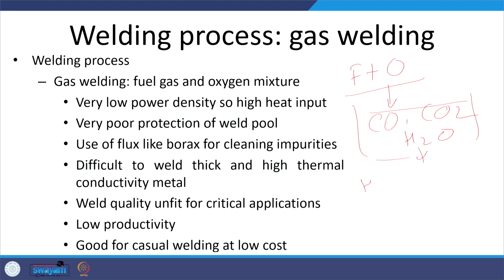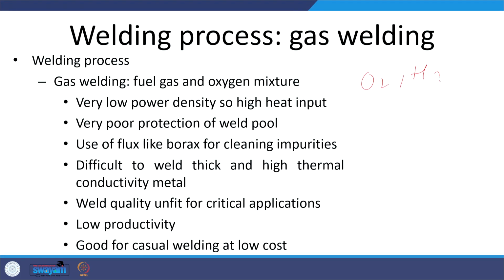These will be providing the oxygen and hydrogen to the weld pool easily, and the protection of the weld pool is affected due to the presence of oxygen and hydrogen around the weld pool, which is produced during the chemical reaction.